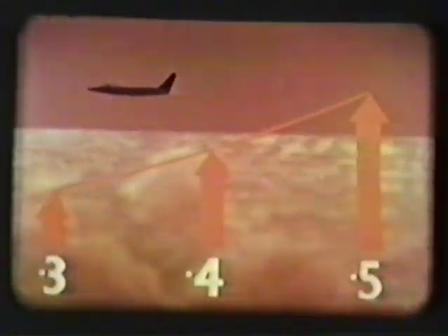The first shock stall trouble is a sharp rise in drag. At speeds below M crit, drag is roughly proportional to the square of the speed. But when shock waves develop, they cause a much greater rise in drag.